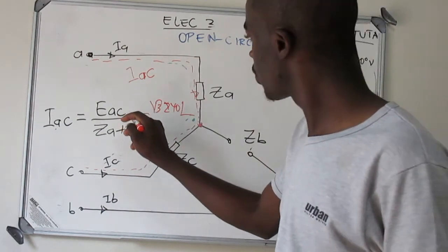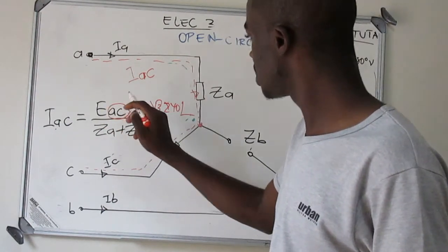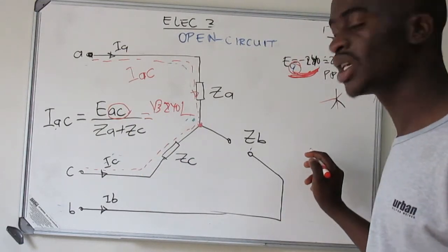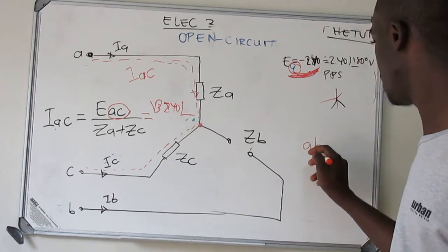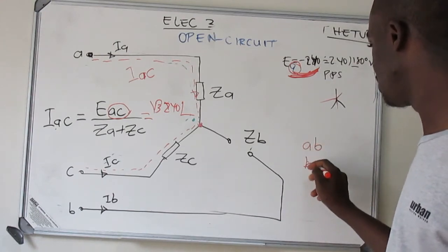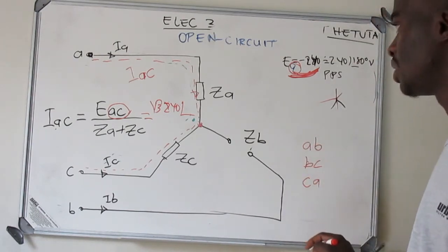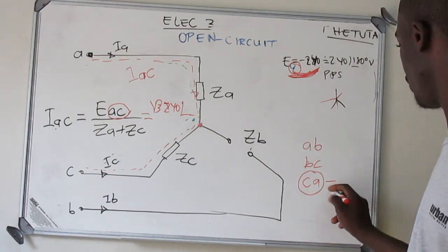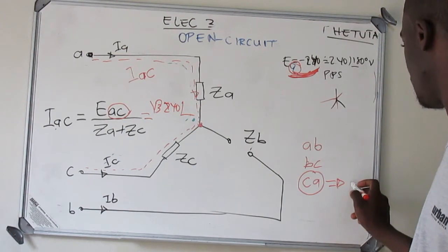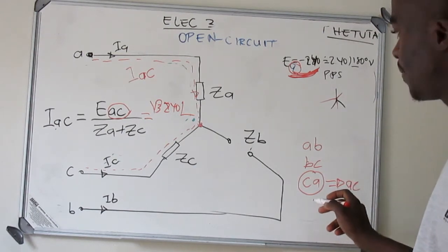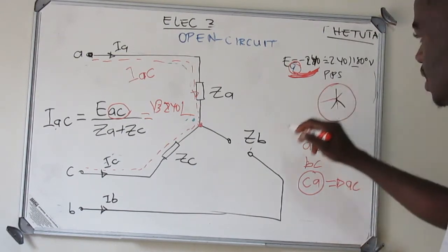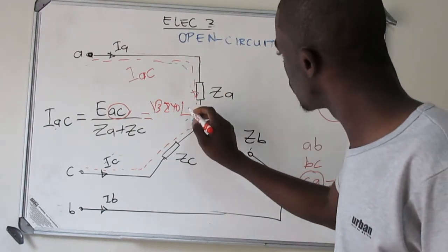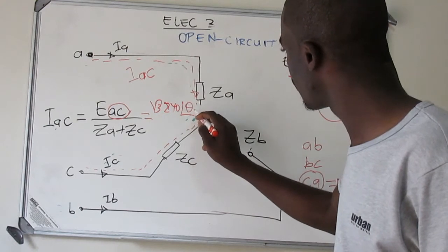Look here. You have a line voltage AC, okay? What are the three line voltages that we always have? AB, BC, and CA. Okay? So which means we have a CA. The inverse of CA is going to be AC. So you're going to go into your phase sequence phasor diagram, and then you take the angle of CA first.